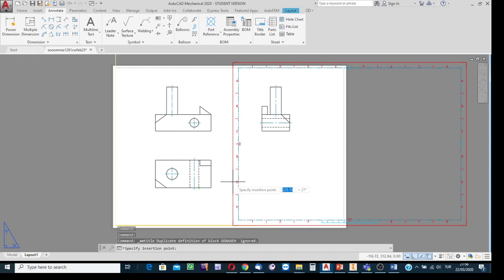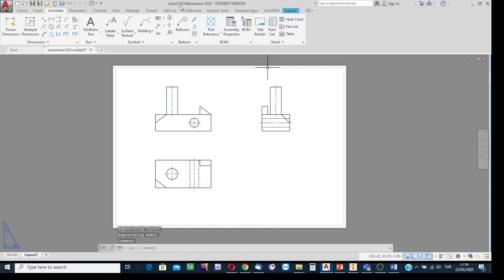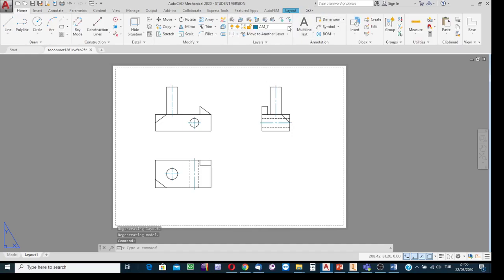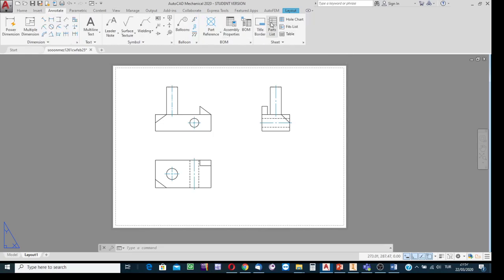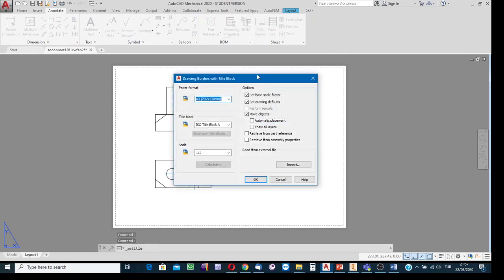Well, actually, I made a mistake. Press escape. First, from this list, select the AM0 layer, not AM7. If AM7 is the active layer, then the margin lines will be in center line quality. In the AM0 layer, AutoCAD keeps and creates the margin lines. Okay, so select this layer and then click on this invoking button, paper simulation invoking.